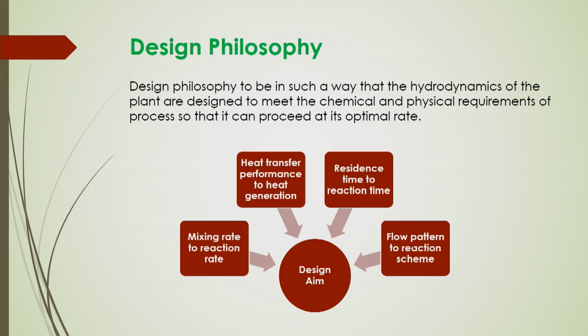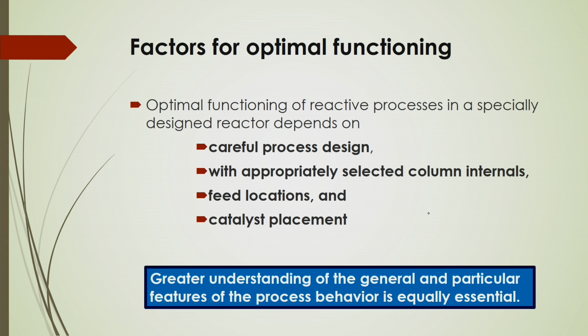All those are different types of flow patterns, and different flow patterns will give you different consumption of energy, based on which you can get the reaction yield or process yield. So, you have to consider this flow pattern. Flow pattern, residence time distribution, heat transfer phenomena, mass transfer phenomena, all those things come as the hydrodynamics part. So, you have to consider all this hydrodynamics for your process design.